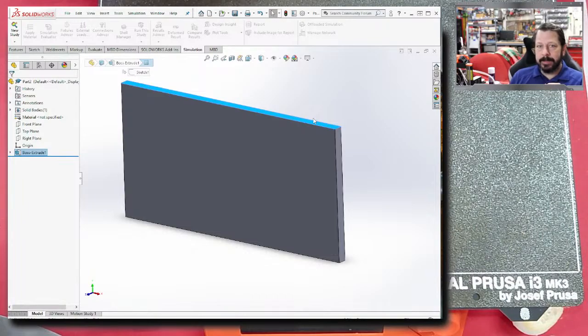Most of the time, you can reduce the weight just by controlling the infill. You can just change the infill amount and control the weight that way, assuming that you still have the strength you need. So FDM and this sort of process are not exactly one-to-one on usefulness to each other.